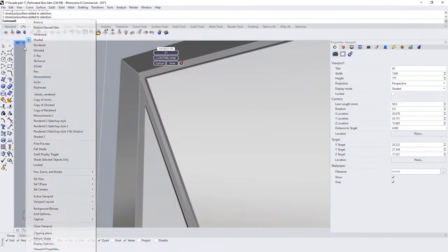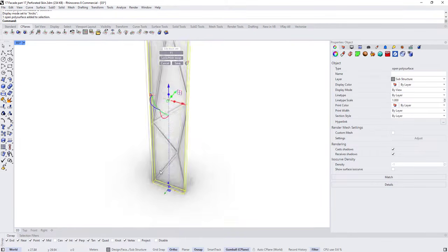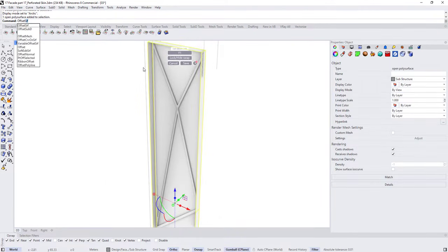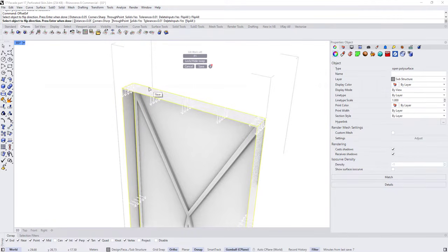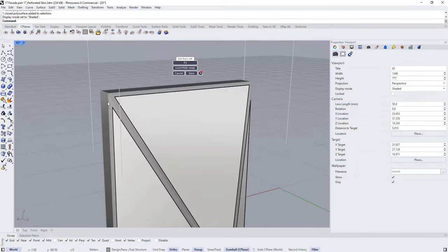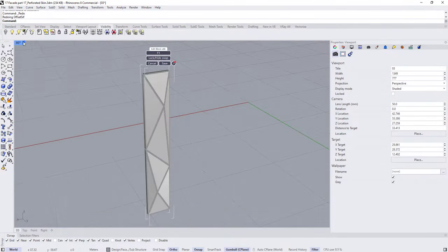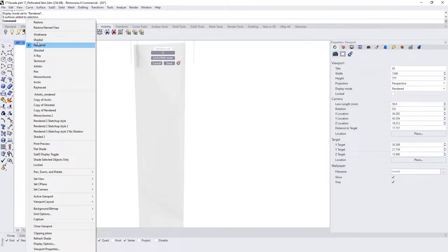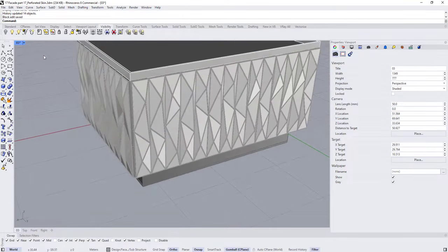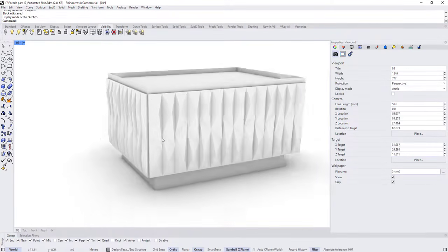First, it's a closed polysurface, which is good. And it doesn't look bad actually. So it's okay. For this one, I'm going to get an offset surface for it alone. Flip all, set distance 0.05. And here we go. So we have our substructure, and these are for the perforated skin. So now what remains is applying texture. Until now everything looks okay.